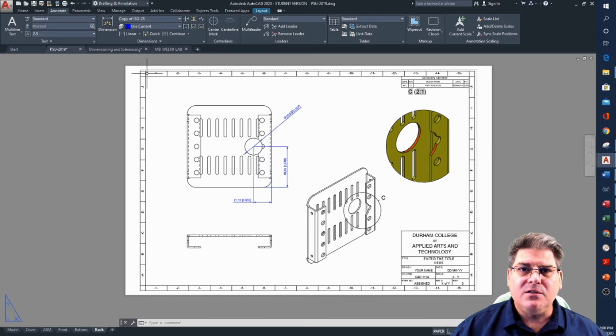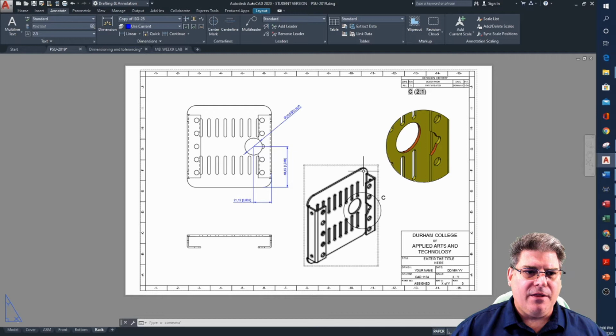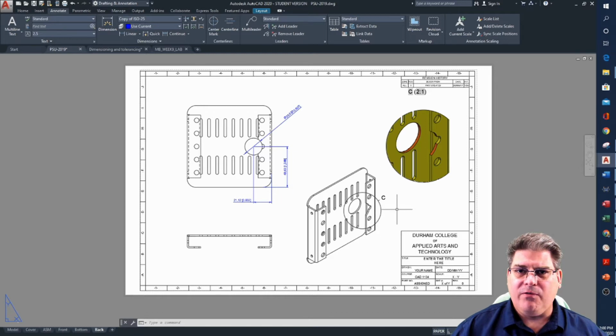Typically it is 25 millimeters or 1 inch, but it can be completely up to you. And by putting this in your template file, you do it once and it's there forever. My suggestion is you do the 11 by 17 and then modify it for an 8.5 by 11. And that way you have it for all time that you can go at and modify it.